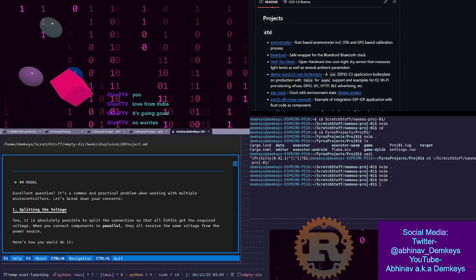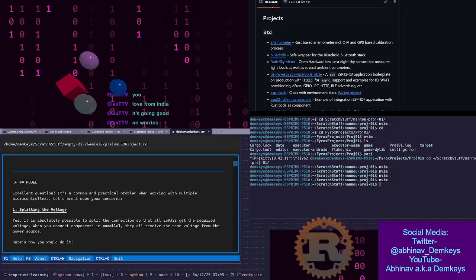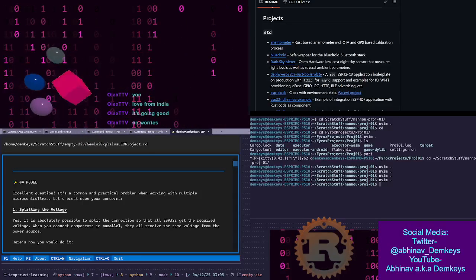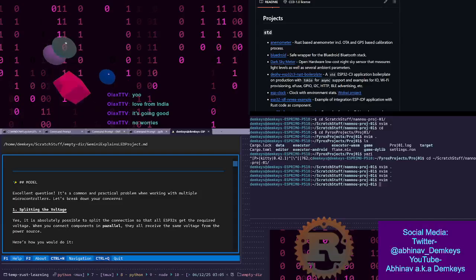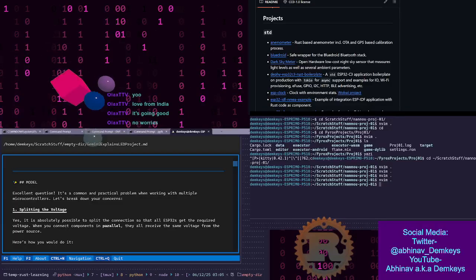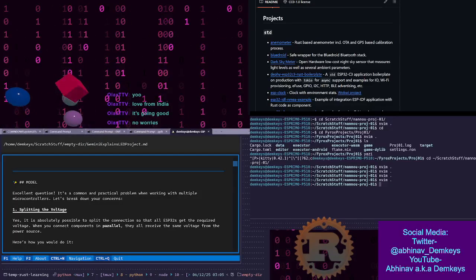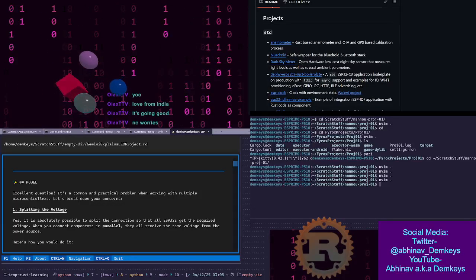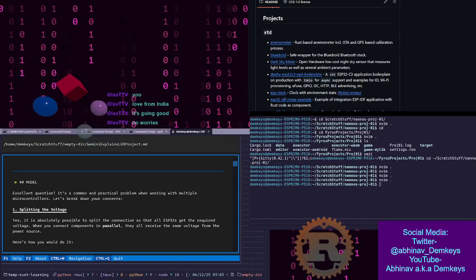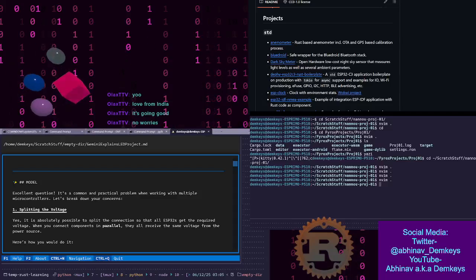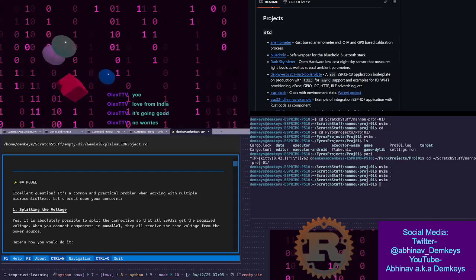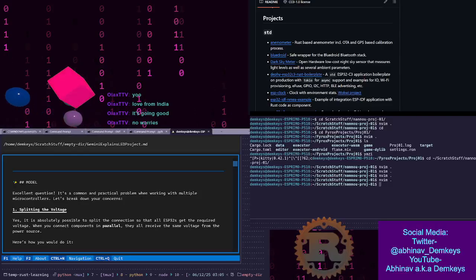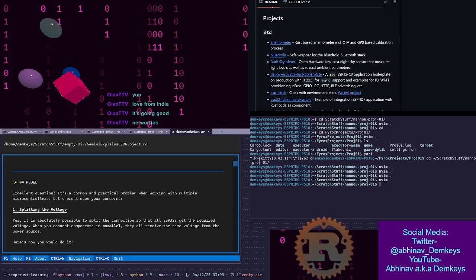But if you're doing a parallel connection, so they're all connected in parallel, all of the pluses are connected together and all of the minuses are connected together, that's a parallel connection. In that connection, the voltage remains the same, but then the current adds up, right? And this is great, but the problem is, at a certain point, you're going to hit the limit of the phone charger. The phone charger can give you usually anywhere between 1 and 2 amps.